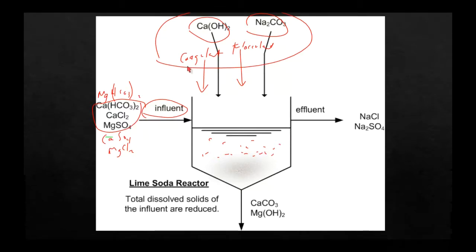They're basically colloids. The coagulant that we add makes them form a small little pin floc. The flocculant that we add brings it all together, and it forms this spongy sludge that accumulates somewhere on the bottom of the vessel. And so we're going to have to blow that off.